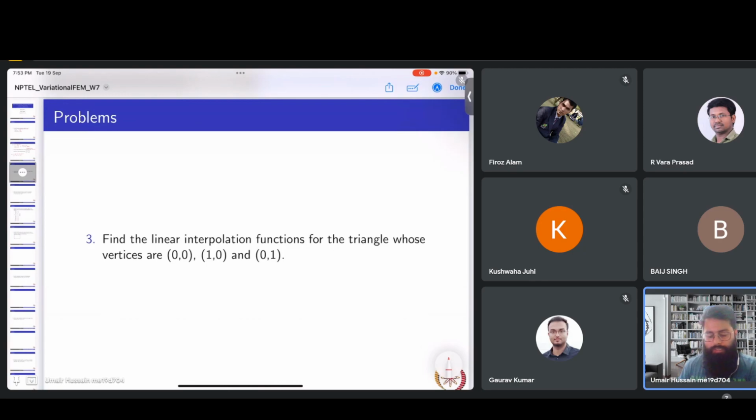Okay, so this here is an interesting exercise. So far, for triangular elements, we saw that if we get the nodal coordinate values, we can form a matrix A based on these nodes, and if we take the inverse of that matrix, we'll get the coefficients of our approximation function. There's one more way that we can do that. I think we discussed that way when we were doing 1D FEM. So we'll try to use that also and see if we get the approximate function.